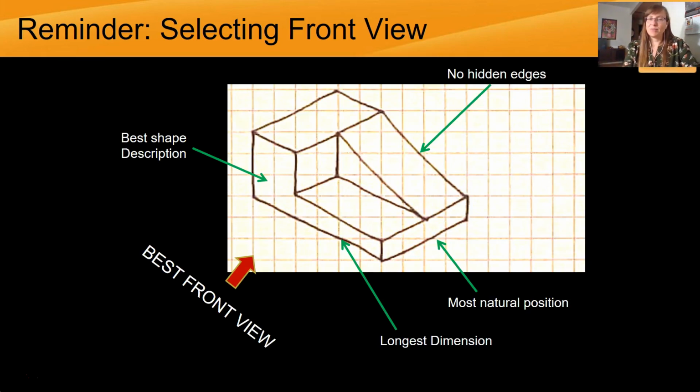So I had shown this slide before as well, but we picked this to be our front view because it is the longest dimension, it has the best shape description, there's nothing hidden in the back, and it is sort of resting in its most natural position.